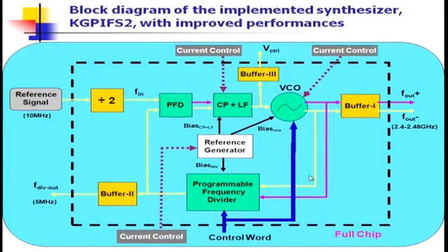So, what I have done, instead of 5 megahertz, I have used 10 megahertz, and similarly the charge pump, loop filters with current control, programmable divider and so on. Some few internal changes have been carried out. It is a divide by 2: my reference is 10 megahertz crystal, which I internally divide by 2 to make 5 megahertz, to reduce the noise contributed from my clock.